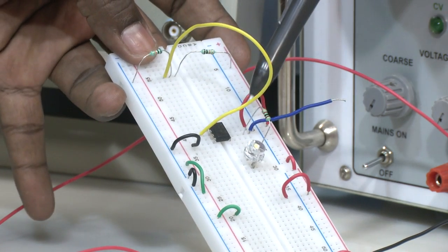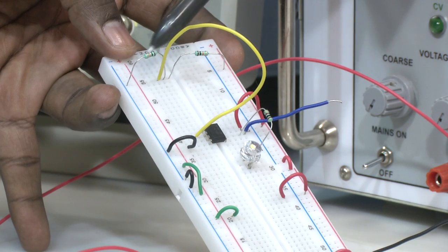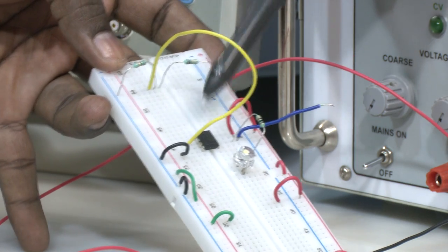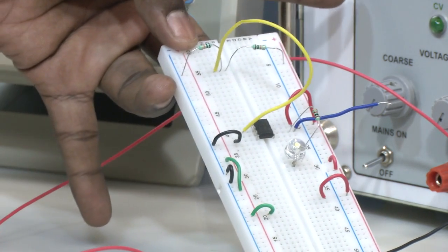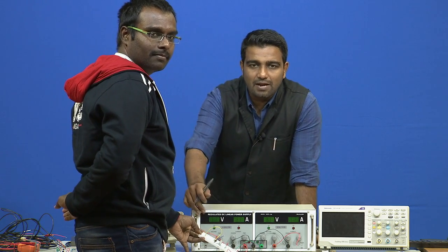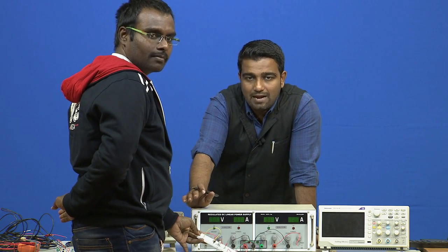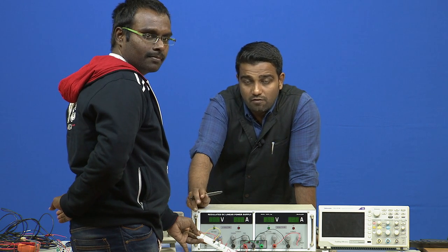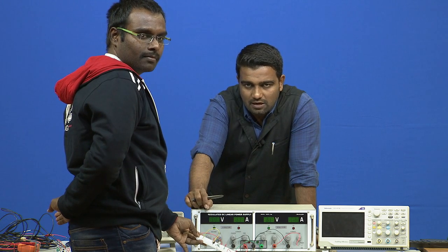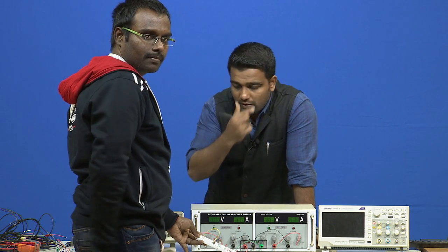So, understand again, output is connected through a limiting resistor to the LED, the inverting input is connected through the potential divider to the op amp. Non inverting input we will apply using the potentiometer or using the power supply. So, instead of this potentiometer, we can directly apply through this DC power supply, right. If you apply 0, 1, 2, 3, you will see at a point when it is greater than 2.5 volts, we will be able to see the glow in the LED, and we will measure the voltage across the potential divider initially, then we will increase the voltage and see what the output is, alright. So, let us perform the experiment.